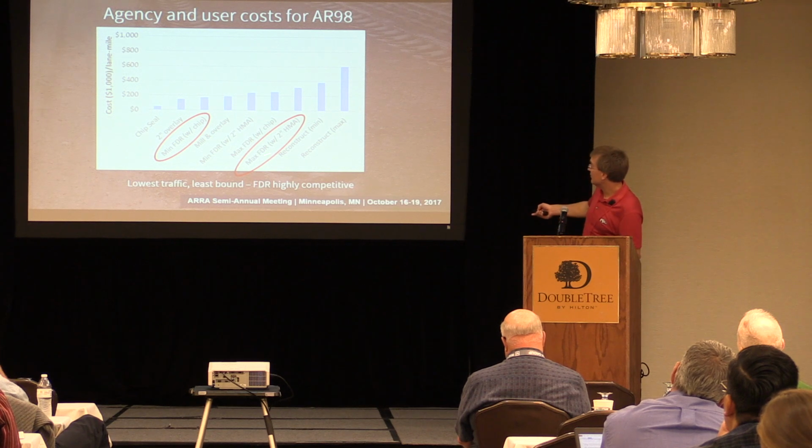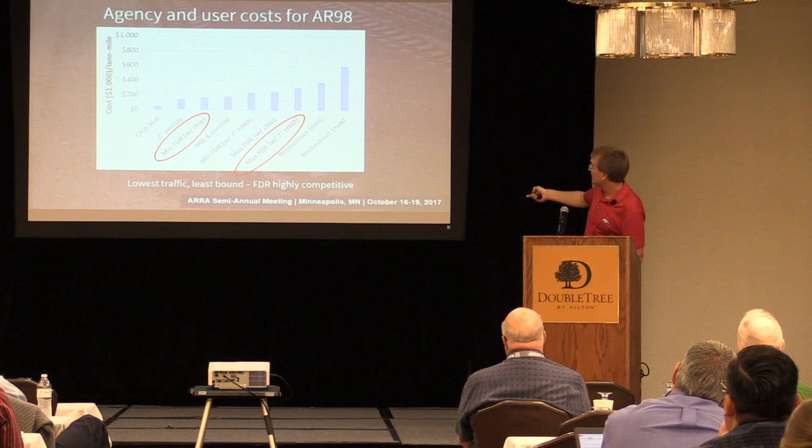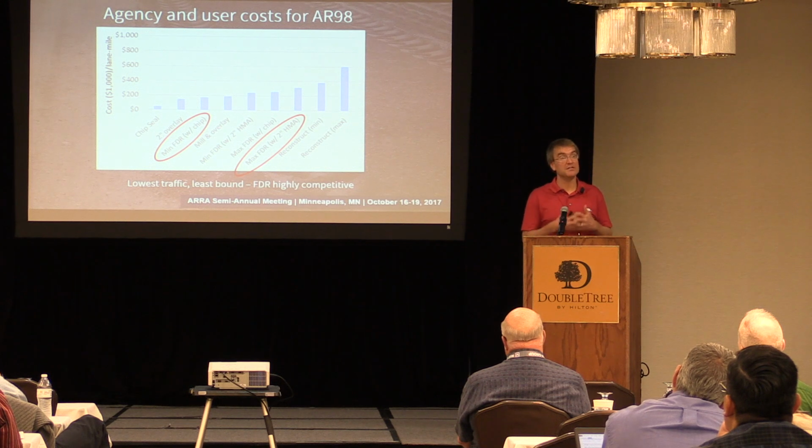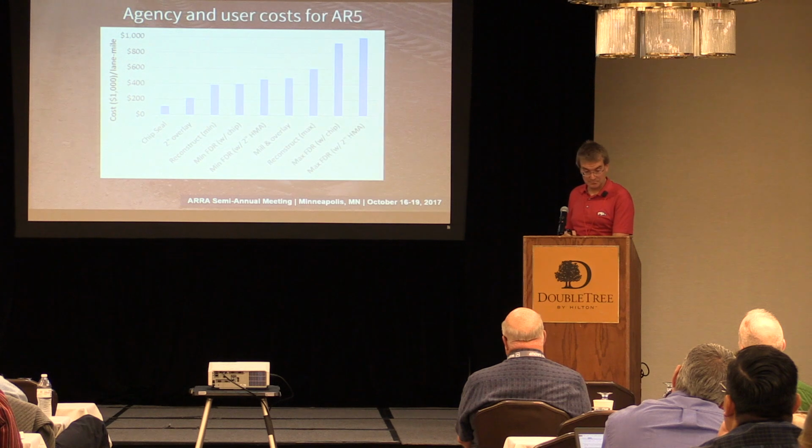And then you can see here, if you want full structural capacity with a 2-inch overlay, that is actually cheaper than even the minimum reconstruct. So AHTD loves going out and ripping out a road and building a new road. And people like it, lots of things are being done, it really shows a big difference, but we're just trying to say that may work on some roads, but on others, FDR is actually a more economically competitive alternative.